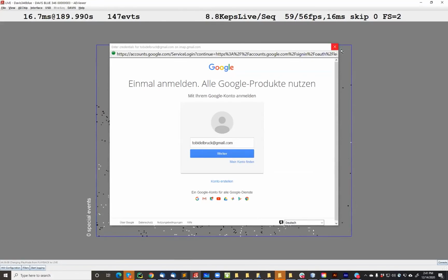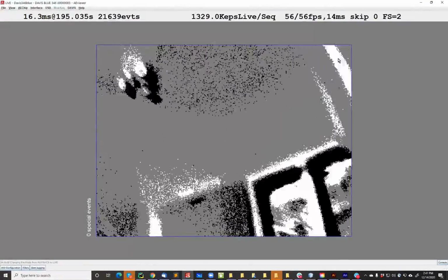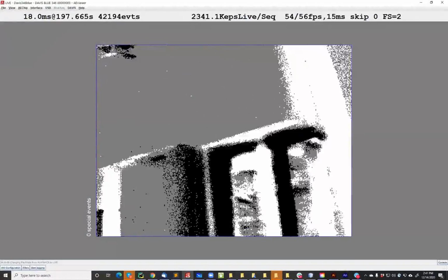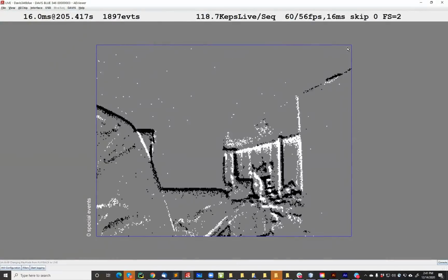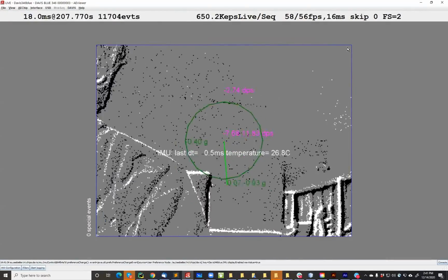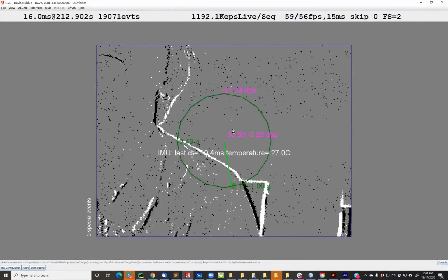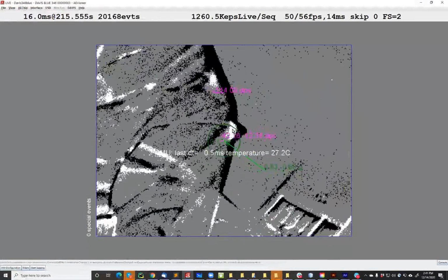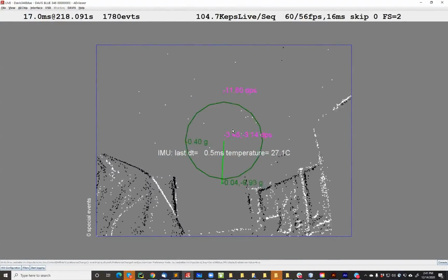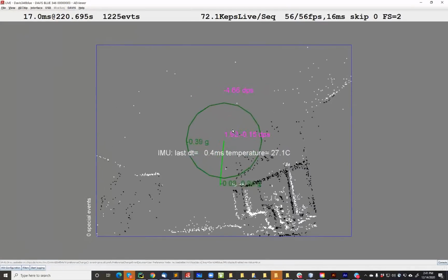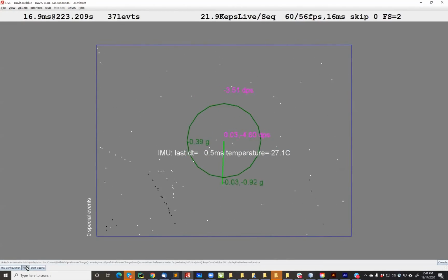So imagine you're in a walking robot, and you're outside and you're walking around like this. You're jiggling around. Maybe you're running actually, and so you're bouncing, right? It's a terribly chaotic view. You have this IMU. There's the IMU output. You see this pink thing here? That's the rotation sensor. It tells you how fast the camera is panning, tilting, and rolling in degrees per second. Now you can use that to compensate for all this motion of the camera. I'll show you how that works.